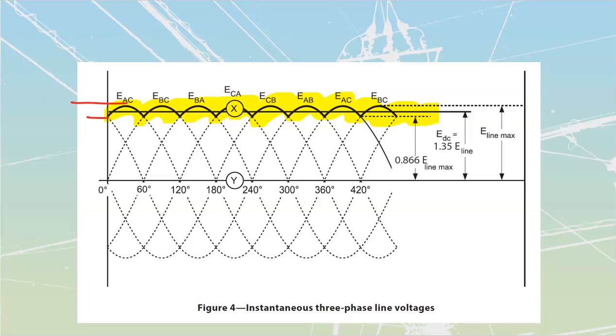If you've driven logging roads before, you get those points where it's washboard. If you hit those washboards fast enough, it's a bit dangerous, but you don't feel them as much because you're just bouncing over top of them so fast. Because of that same sort of effect, we want this on large DC drives. We will use full wave rectification. We're going to use thyristors to power everything forward. We're going to use those SCRs that we talked about, and then we're going to start chopping stuff up.